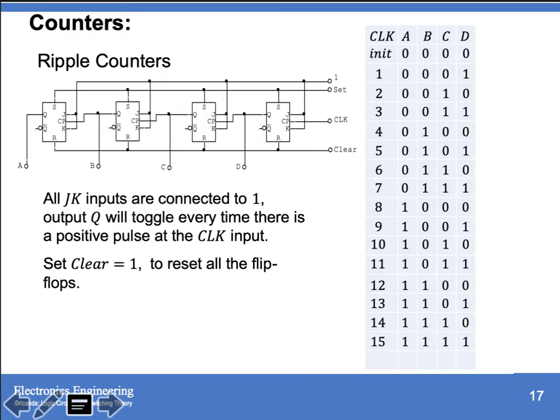On the 16th cycle, your D will toggle since D has an output of 1 before the 16th pulse occurs. So therefore, C will toggle. Then this also will toggle your D and your E will also toggle, that is a ripple effect. So your 16 now has a value of 0 for your E, B, C, and D. So it means that in the 16th pulse, your sequence will return to its initial value.